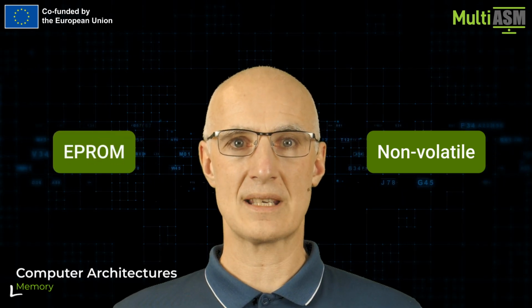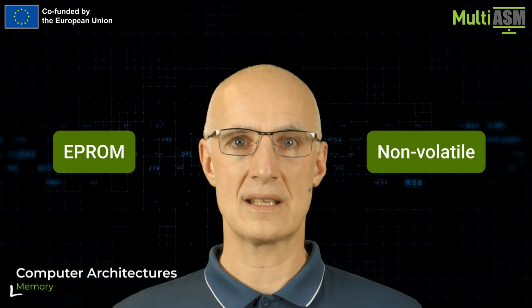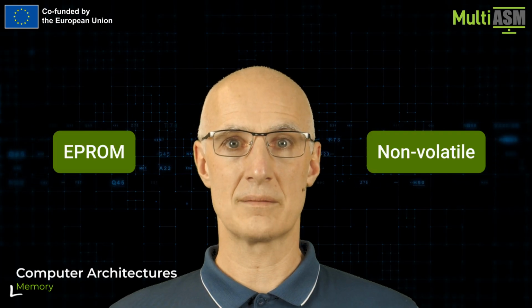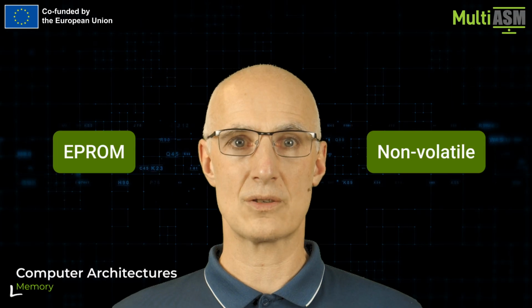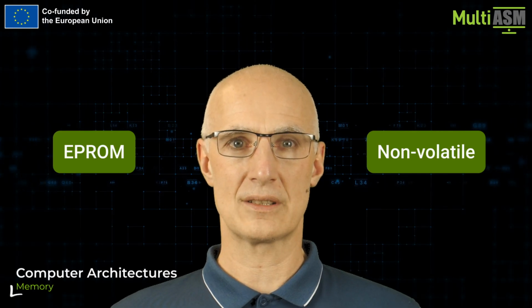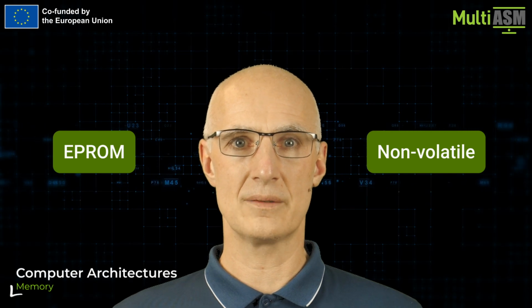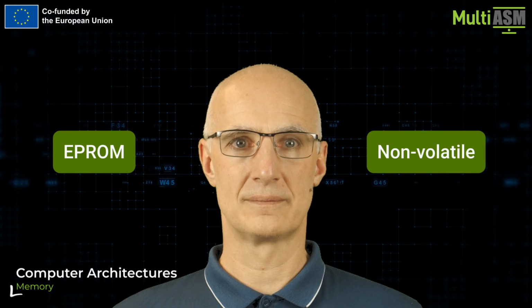EPROM, erasable programmable read-only memory, is a memory which can be programmed and erased many times. Programming is performed electrically and erasing is done by shining an intense ultraviolet light through a special transparent window into the memory chip for a few minutes. After erasing, the chip can be programmed again. The content of EPROM memory can be lost if exposed to solar light, so the chip window should be protected from direct ultraviolet or sunlight.